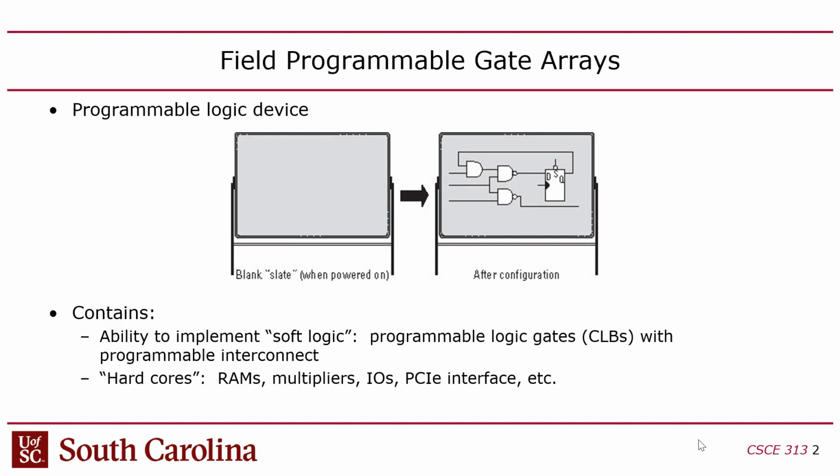You can actually reprogram that flash directly from Quartus, although it's best that you didn't, because I don't know how to restore the original configuration to that thing. And what may happen is if you program it with a bit stream that doesn't do anything obvious, then someone will turn the board on, it won't start blinking, they'll think the board is bad, right? Even though it's not, it just hasn't been programmed with that configuration. Okay, so